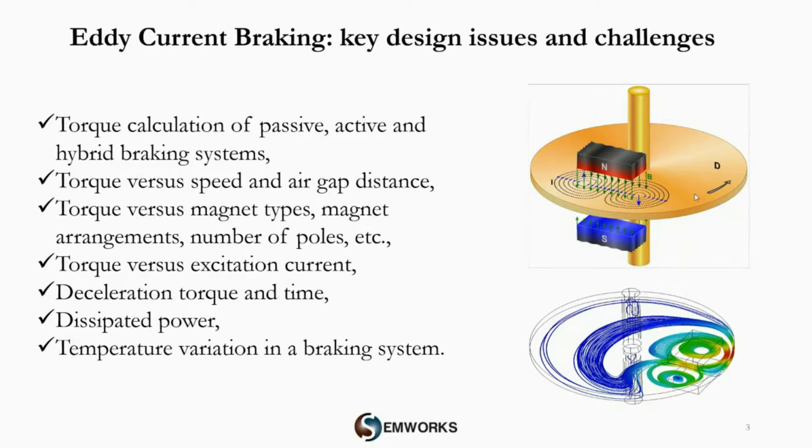Of course, if the disk is made of steel, you can also have core losses. That's another design issue: steel is stronger mechanically, but then you could also have issues related to core losses.